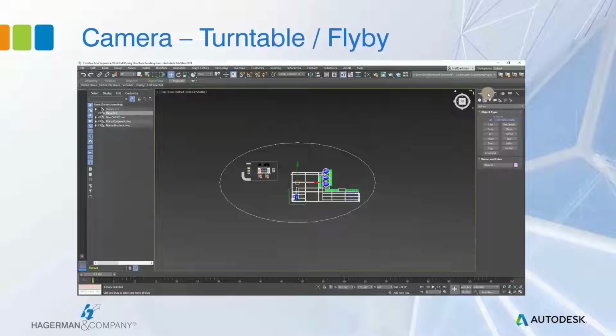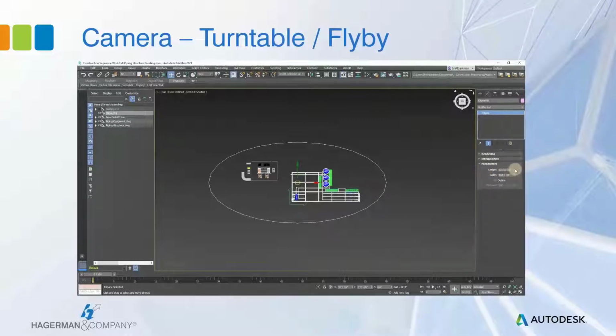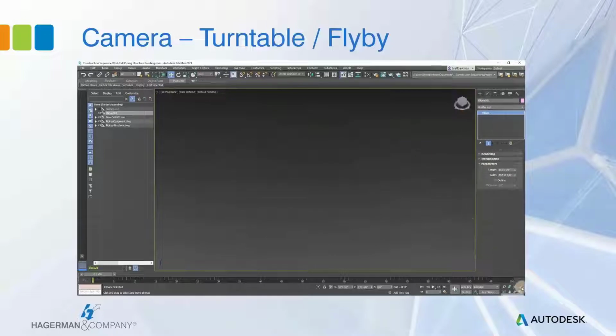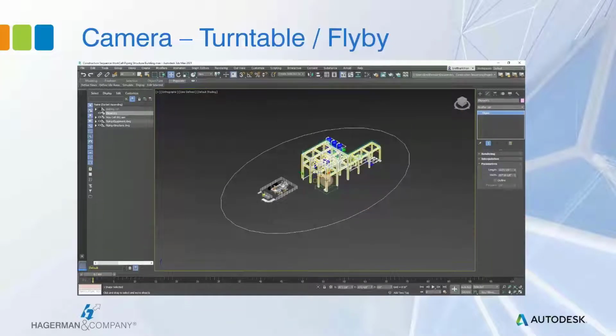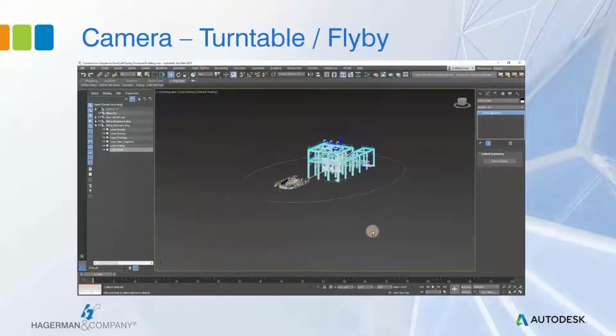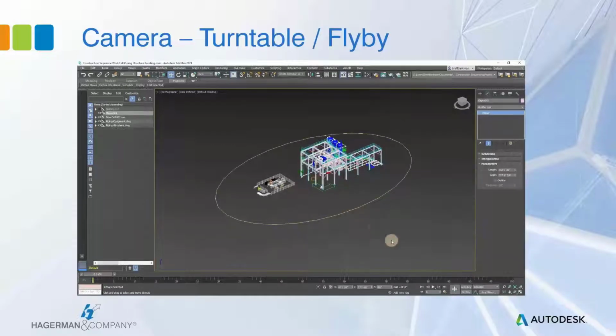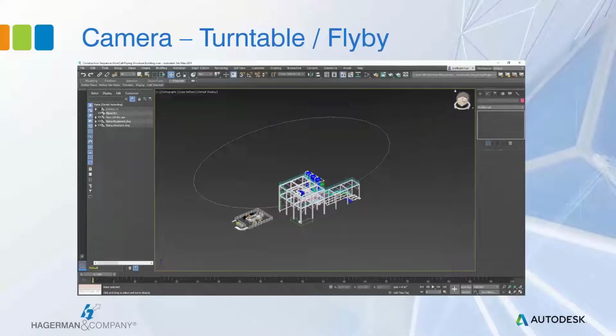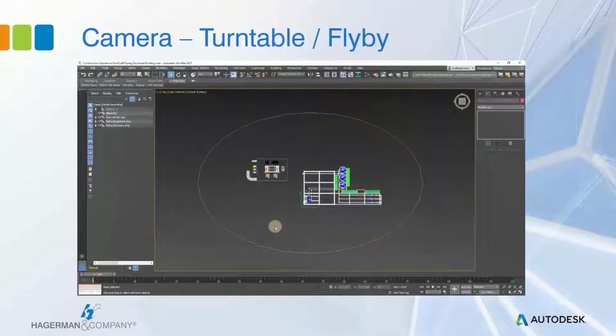To change the size, I'll use the tools on the Modify panel. The ellipse will be on the floor at first, so once I get the size that I want, I will need to move it up where I want the shot to be. As you can see here, it is still down on the floor, but we want this to be more of an aerial viewpoint. So I'll make sure that ellipse is selected, and then use the slider wheel for the Z-axis down at the bottom of the screen to elevate it. You could enter an exact value there if you want, or you can use the slider arrows and do it freehand.